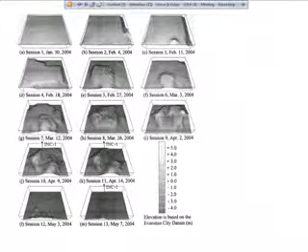The other thing we can do with these laser scans, and this becomes really critical, is when we look at the end of a project, we typically have a series of as-built drawings, or sometimes an as-built model. But that doesn't take into account the process they went through to get from point A to point B. What we're looking at here on screen is an excavation, and they took a series of laser scan snapshots throughout the project. So at the end of the project, not only do we have the as-built, but we have an archive of the whole construction process.